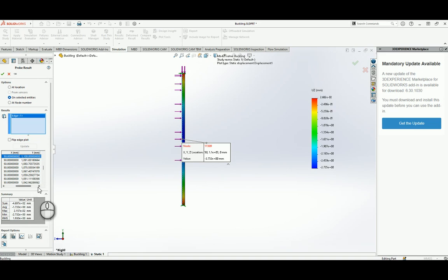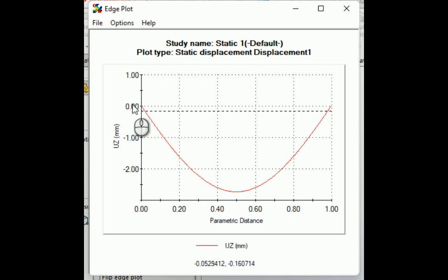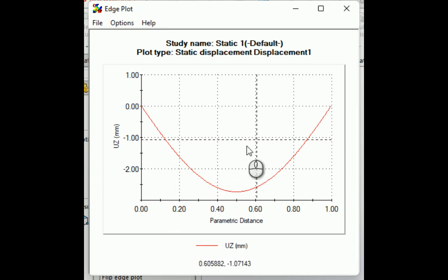Right, so anyway, what I wanted to show here is that you could come to the bottom here and click plot. So you could actually plot the curve. What we did, we plotted the distance for the entire beam here. Right, this is a parametric distance. What this means is that at 0.8, you multiply 0.8 by 2.2 to get the distance in meters. Right, 1 really here is 2.2. 0.4 multiplied by 2.2 will give you this distance here along the beam.